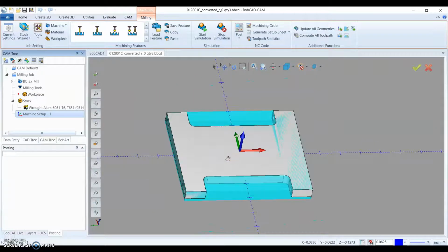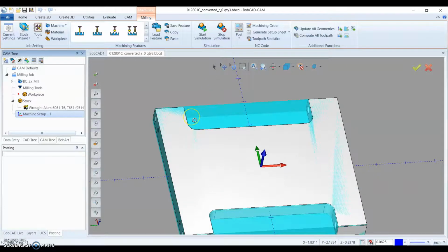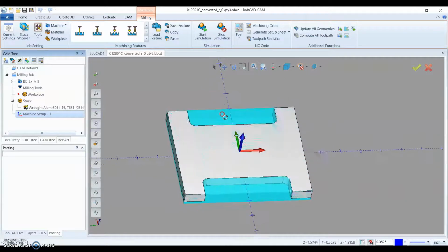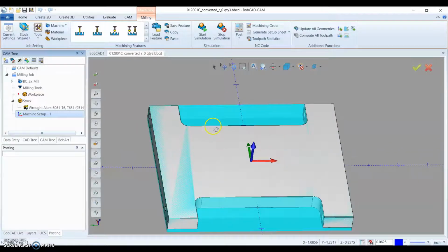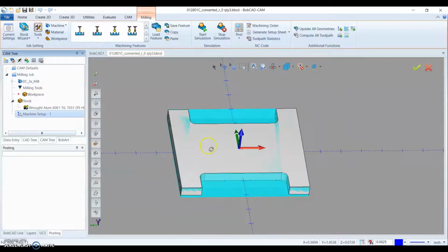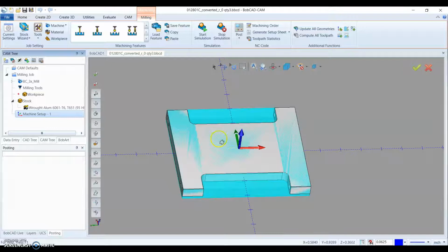We've got two basic ways of doing it. We either do this 3-axis or we can do it 2-axis. I think in general 3-axis is the better way because it knows where your material, your stock is, or your model, and it doesn't really allow you to make a mistake and machine something you didn't intend to machine.